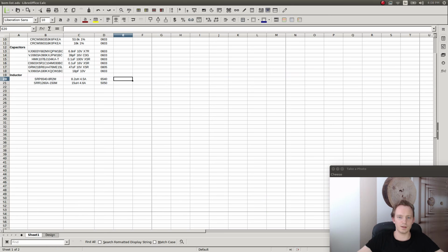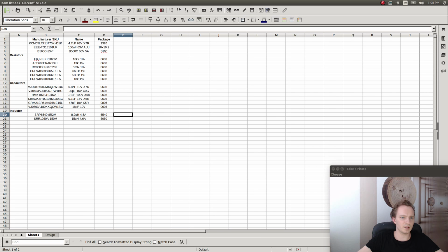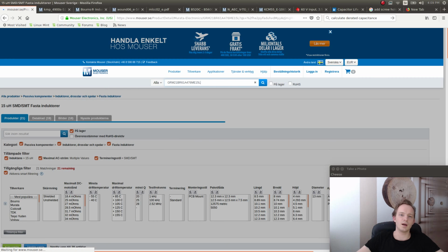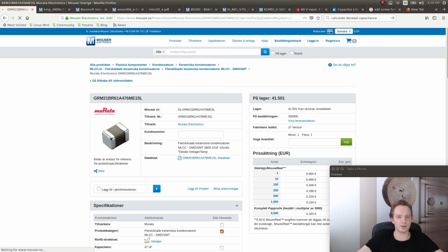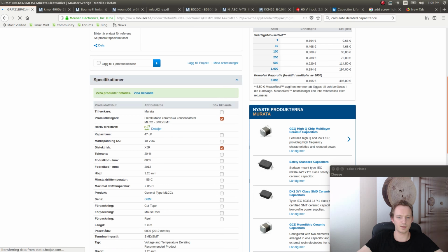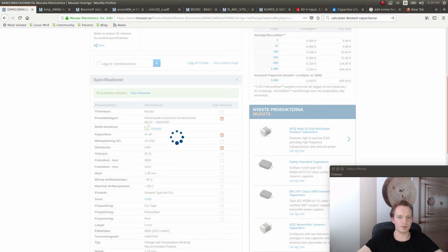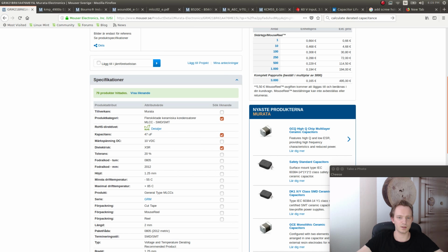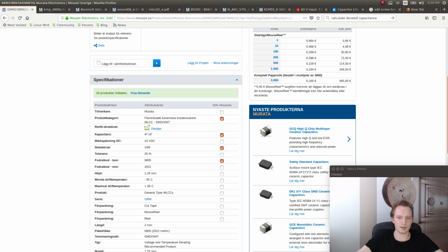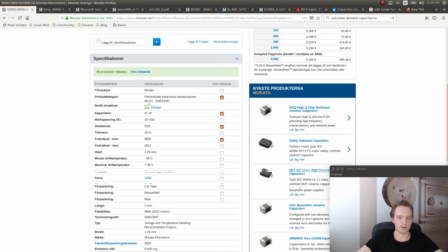And what I'm going to do is go back here and pick the capacitor that we've chosen for 47 microfarads, and search for that capacitor, and then I can search for similar capacitors. So I can search for X5R and 47 microfarads, and I get 79 choices, and I can pick the package.